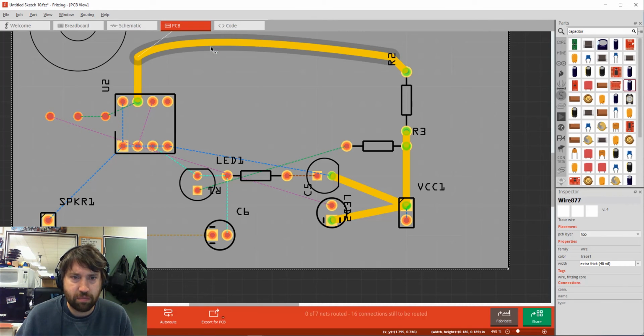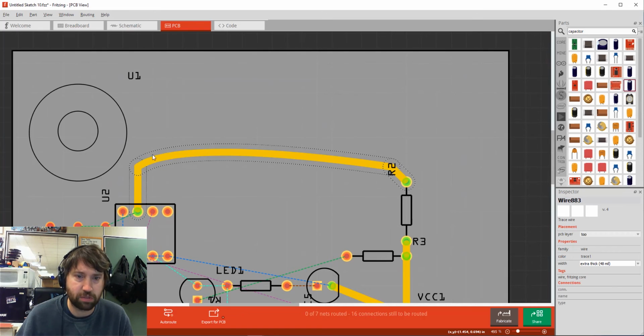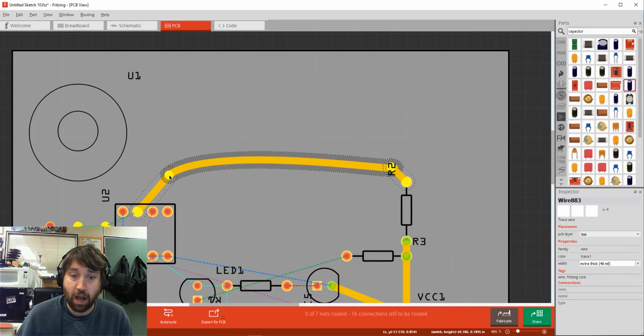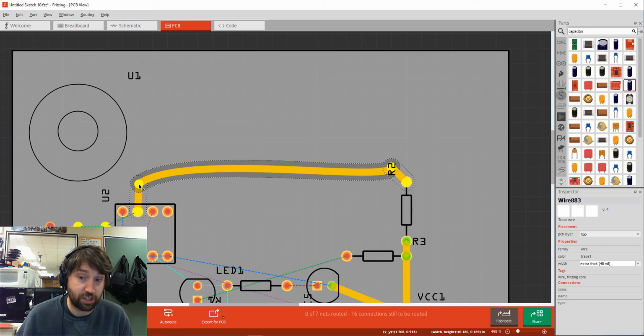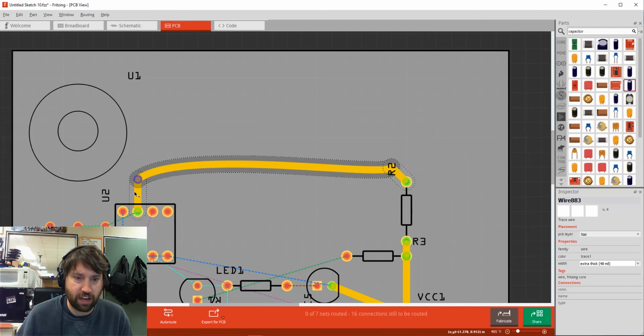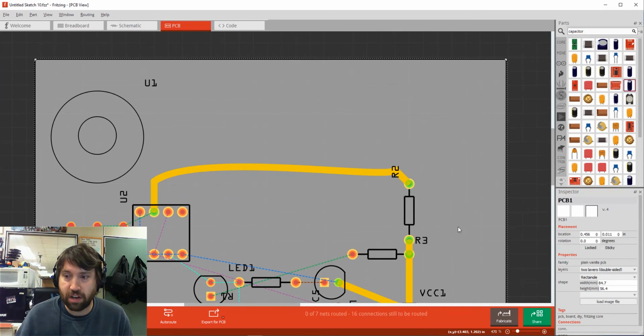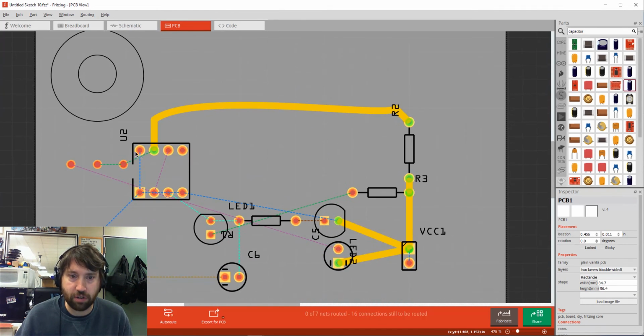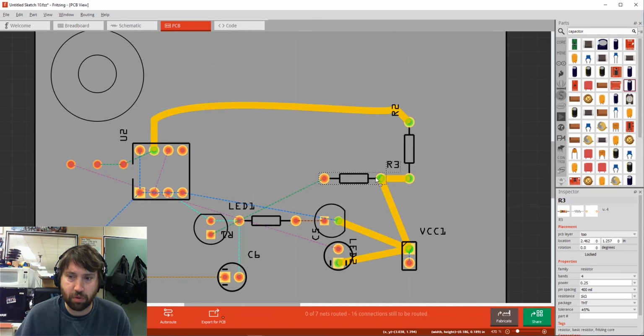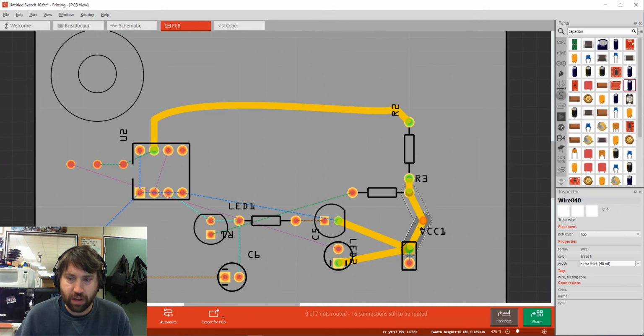I find that making curves and editing them in Fritzing isn't super intuitive, and maybe I just need to spend some more time to get good at it. I'm not sure. But the best solution is actually to introduce curves if you can, for any of the times that we're changing directions. Straight lines, of course, are great. And in my solution, I ended up making it all polygonal, but just trying to avoid right angles wherever possible. Okay. The last thing to consider, so you'll have some solving to do, and once you've made your traces, you can still move the components around, and you can always adjust, or either add new traces or adjust the path of the traces.